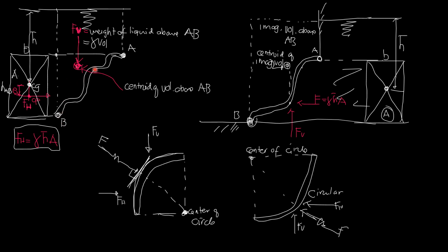If it is circular, a quarter circle for example, this area would be area of square minus area of quarter circle. If it is parabolic, then this may be a spandrel of parabola, and it is 1/3 of the base times height.